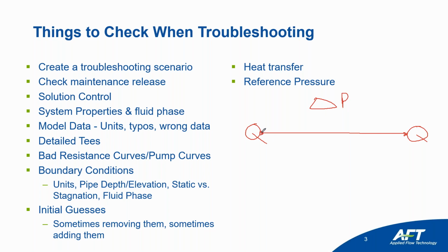But what's the pressure at the inlet of this pipe, or the outlet of this pipe, or the middle of this pipe? It's unknown. The reason why is because there are multiple solutions for pressure that exist that will give you the required dP to drive that flow.